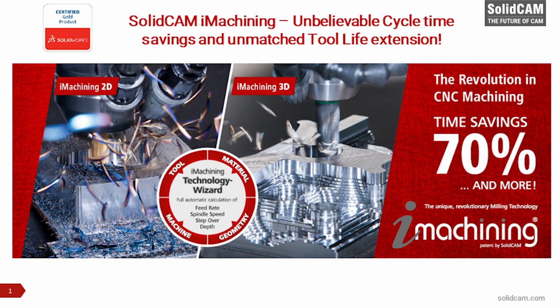And that's sort of a balancing act that you can play. So for instance, when I'm cutting aluminum, I can use pretty much all the way up to the 80 degrees without any difficulty at all. If I'm cutting in titanium, I typically bring it down around 35 to 40 degrees. If I'm cutting in D2 or similar hardened tool steels that range up into that 45 to 52 Rockwell C, sometimes I'll bring that down even lower, like to 30 degrees.